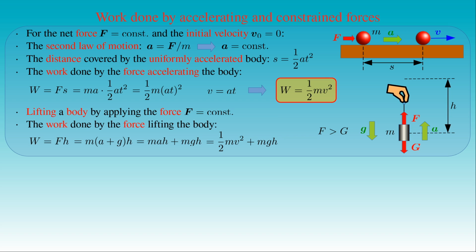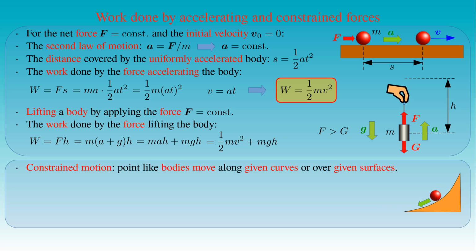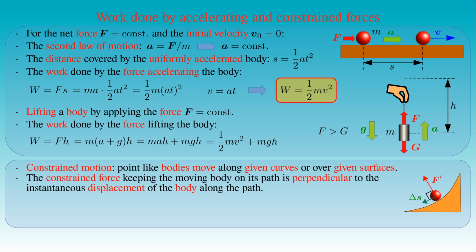We also need to mention the other general case of the work done by constrained forces. When we studied constrained motion of a point-like body, we saw that the body moves along a given curve or over a given surface representing some geometric constraint imposed on the motion. The constrained force F' keeping the moving body on its path is normally perpendicular to the instantaneous displacement delta s of the body along the path.